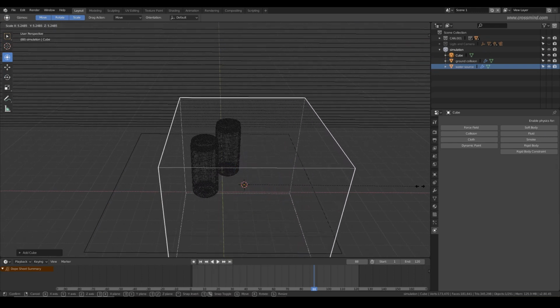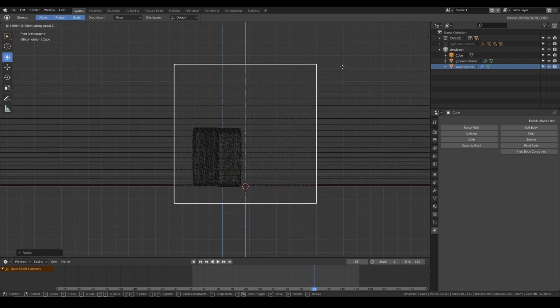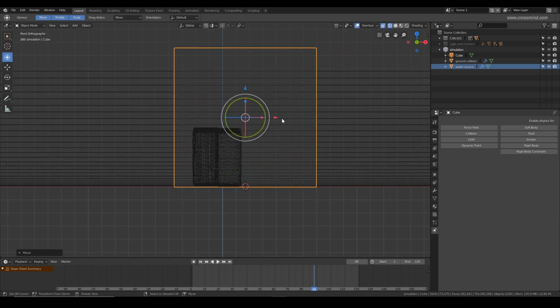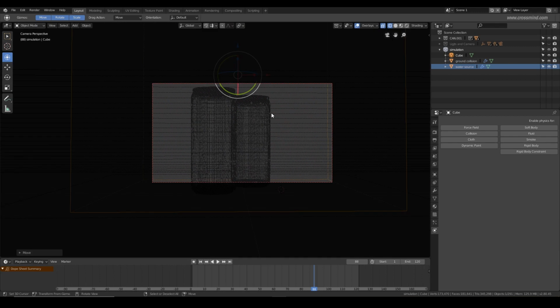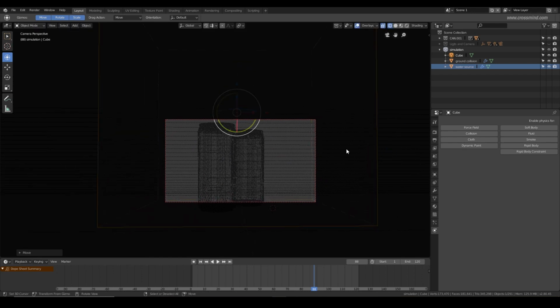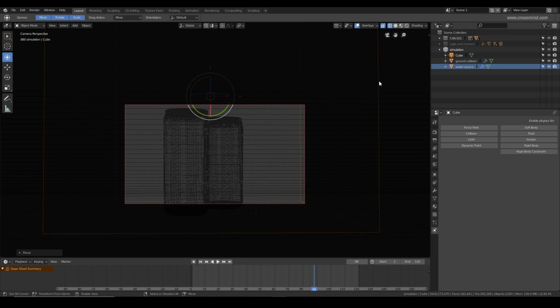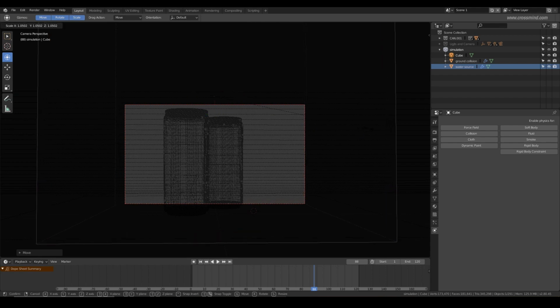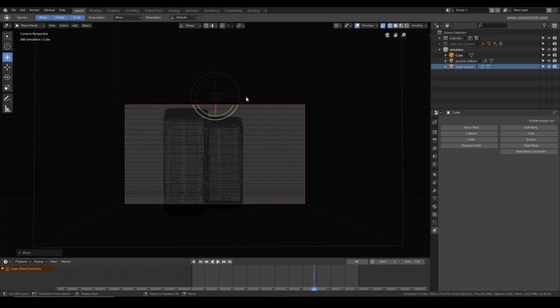Let's create our domain object, place it right in the middle, and make sure the width is just enough to cover our frame area which is seen in the camera. As you can see, the back side of the cube is covering the entire frame very well.